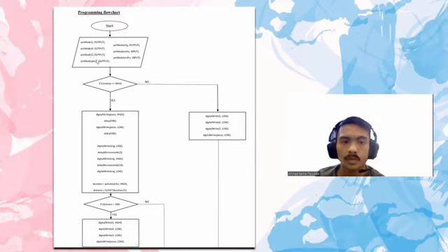And the pin mode piezo indicates the buzzer. And pin mode 3 indicates the trigger function from the ultrasonic sensor. And then for the input, we have 2, which is the echo, where the input is triggered from the echo function of the ultrasonic sensor. And the last one is the CTS pin, where this input is triggered from the capacitive touch sensor.